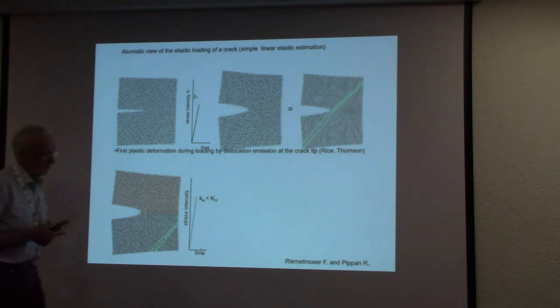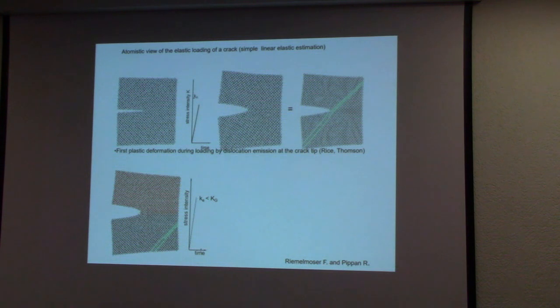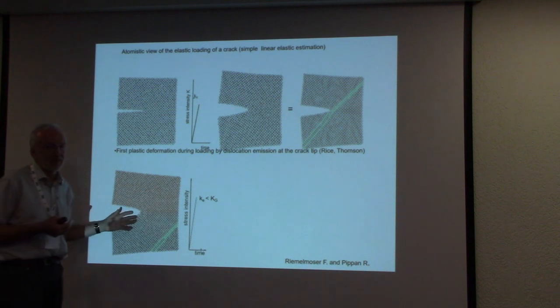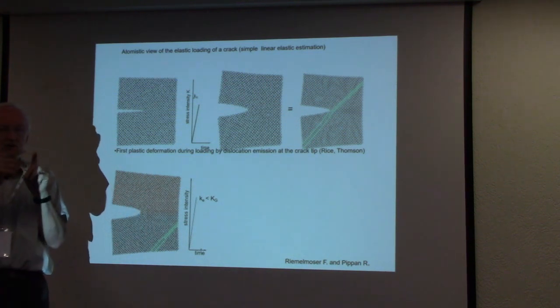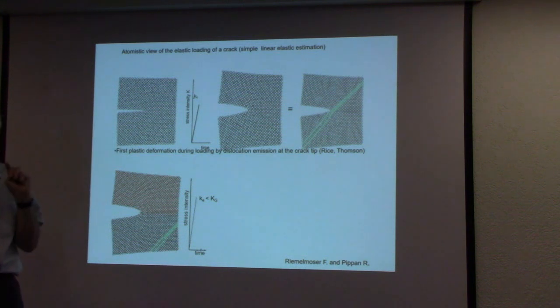One of the things continuum mechanics groups have done is to use crystal plasticity, where they take into account the single slip processes, but even this crystal plasticity concept cannot be used on this scale. It can only be used on scales which are large compared to the spacing of dislocations, and it cannot describe, for example, the size effects.